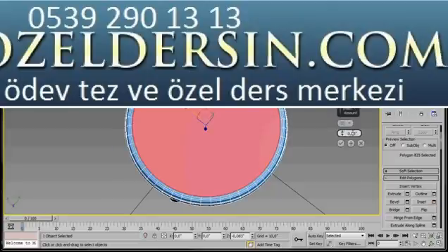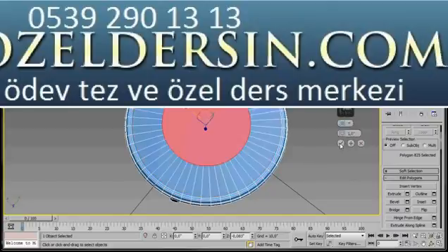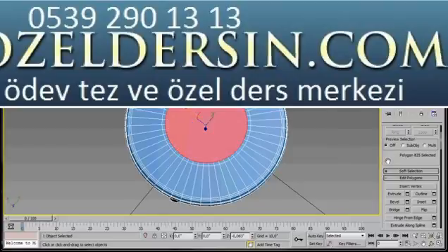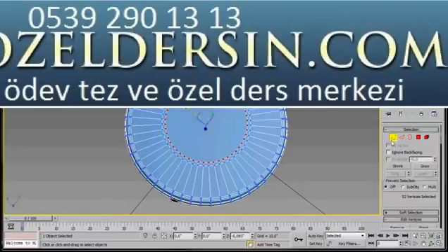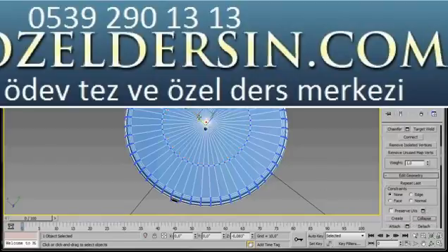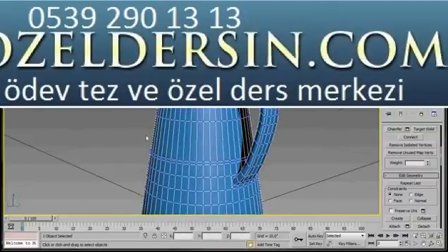We're going to create another inset. Just type in 1, then press OK twice. We can create a third inset. This time we're just going to type in 0.1, then press OK twice. OK, keep our polygon selected, hold the Control key down and we'll scroll up to Selection and press Vertex mode. This has just converted our polygon to vertices. Now we're going to scroll down and click on Collapse. We've just collapsed all our vertices to one vertex. Very good, let's orbit around.